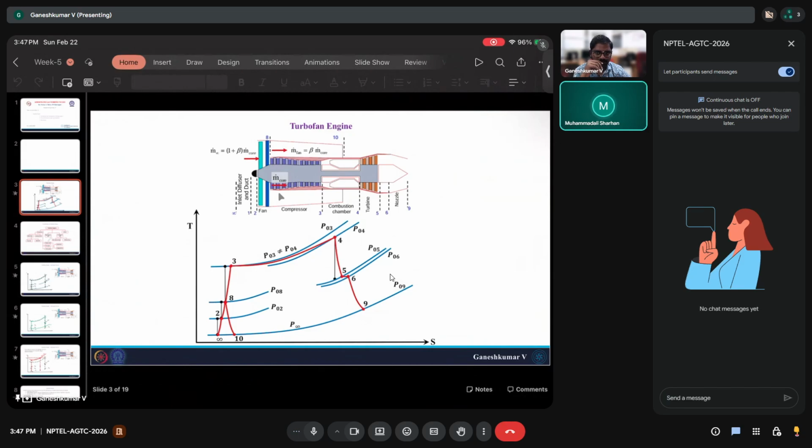Along the blade length, the angular velocity will change, right? Yes, along the blade it is true, but that effect will not come into this. That will be very minor. So across the fan your pressure is going to rise. Also, we are dealing not in terms of static pressures and static temperatures, but in terms of stagnation pressure and stagnation temperature. So we are not really worried about exactly what the velocity coming out of the nozzle is, or what the pressure of the air coming out of the nozzle is. We are just worried about the stagnation pressure and stagnation temperature.